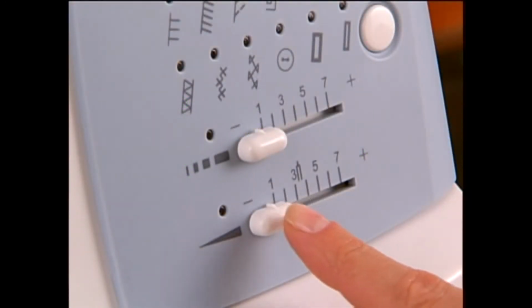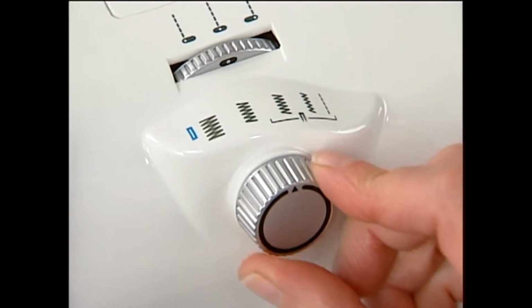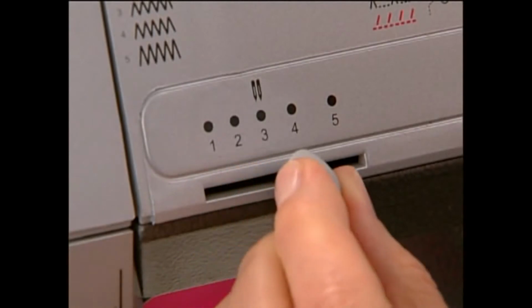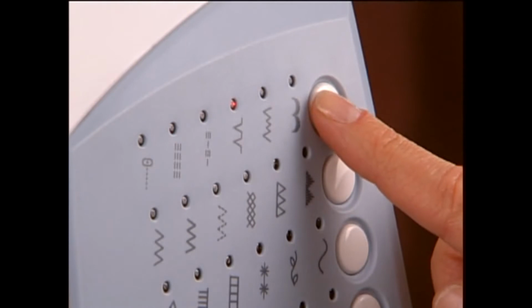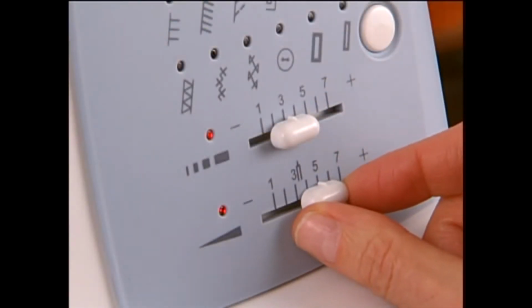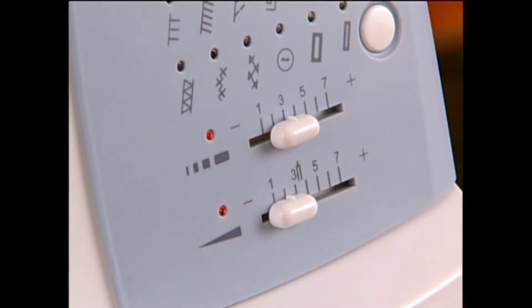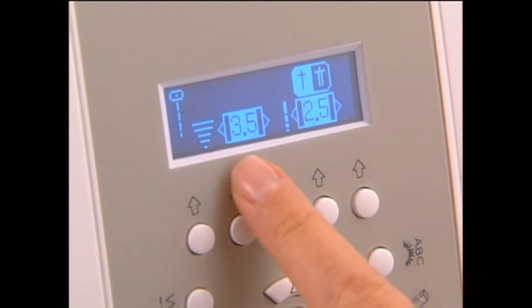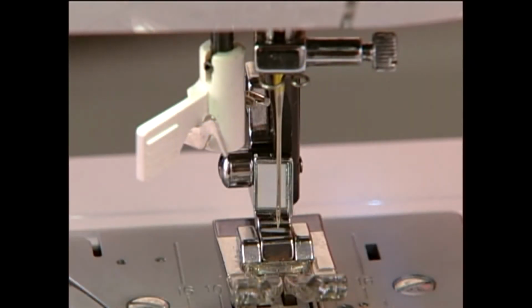The stitch width control can be set to make stitches sew narrower or wider, depending on the look you want. For mechanical machines, this is done by turning a dial or lever. For electronic or computerized machines, though the optimal setting is set upon the selection of the stitch, further adjustment of the stitch width can be done either with a lever or by push button. For most machines, you can also use the stitch width control to adjust the position of the needle when the machine is set for straight stitch.